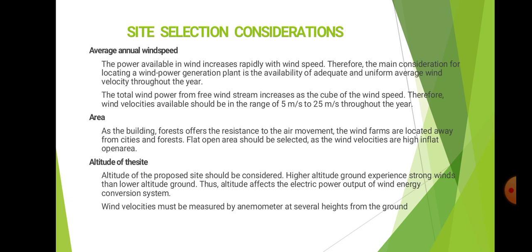Then we select the area. As buildings and forests offer resistance to air movement, the wind farm should be located away from cities and forests. A flat open area should be selected, as wind velocities are high in flat open areas.